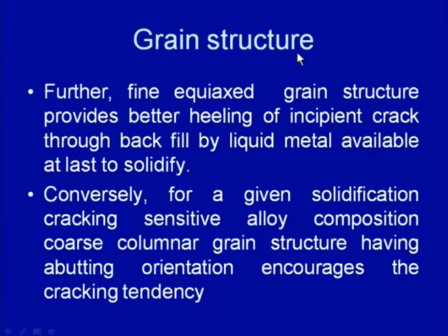Now, we will see the effect of the grain structure on the solidification cracking tendency. We know that if the grain structure is fine and equiaxed, it will provide better flow of the liquid metal available for healing the cracks which are being developed due to the localization of the tensile stresses.